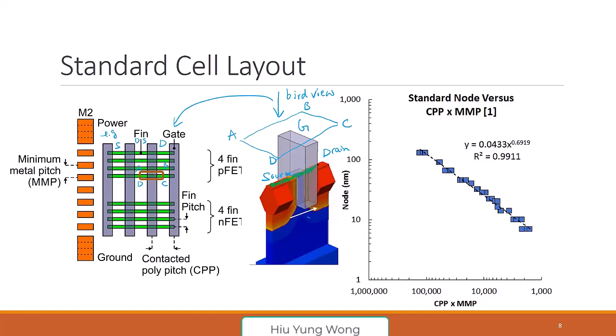This is the green line you see from top. Now, do not match this directly one-to-one. For layout, you are not going to draw this diamond. This is something that grows from the fin in the process, but you don't need to draw it. After fabrication, you will get this diamond. But if you want to compare, this is the one.